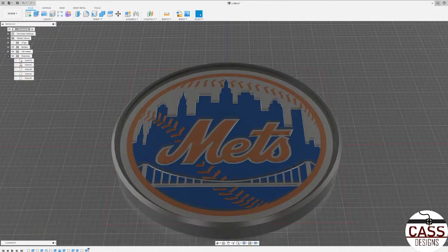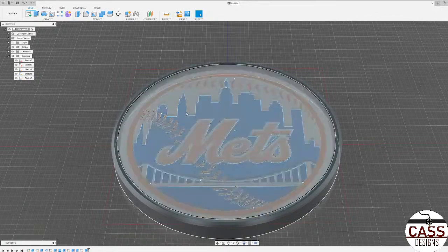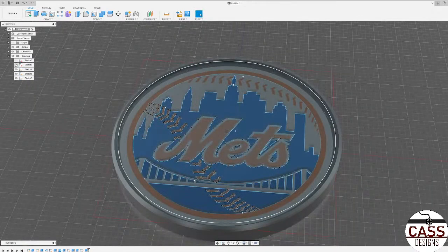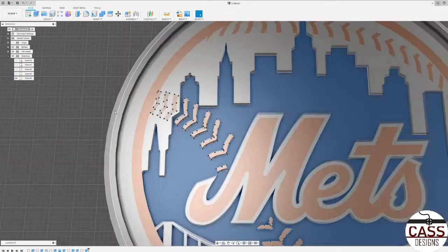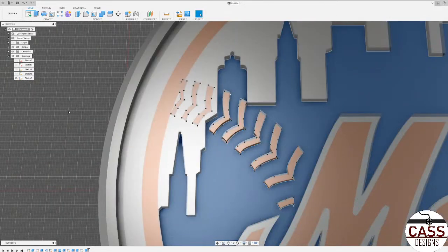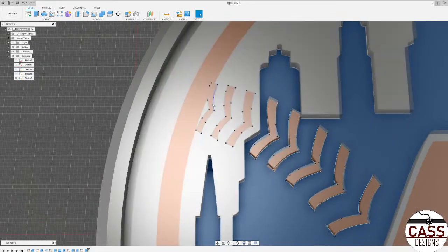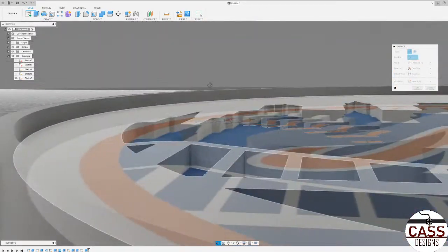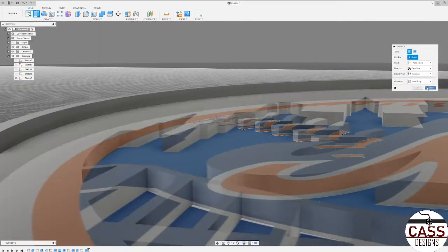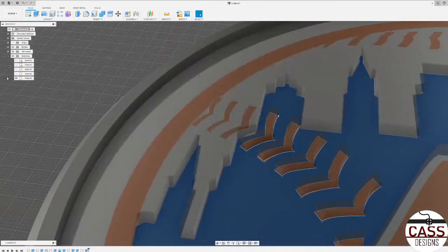And then sketches. Usually when you finish a sketch, if I highlight all these, it's a lot of blue and a lot of ugly things you don't want to see, so it automatically hides them. For this, we want this to be shown again because we want to reuse these bodies here. So now that this is showing, if I click E again to extrude and click profiles, you can't really grab it because it's underneath this surface that it wants to grab automatically.